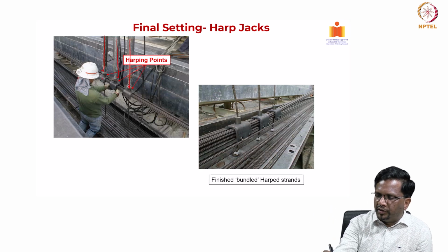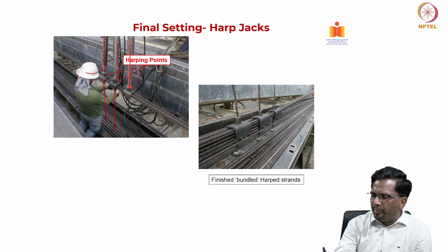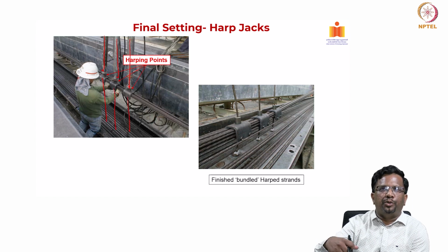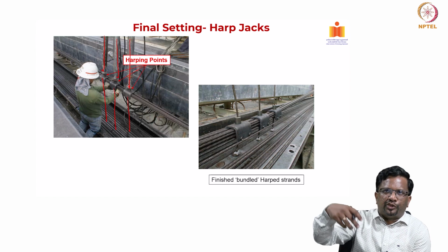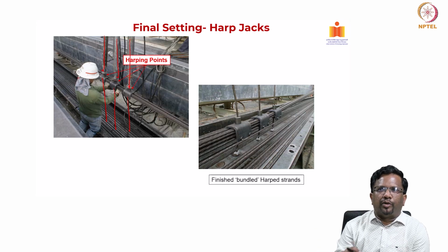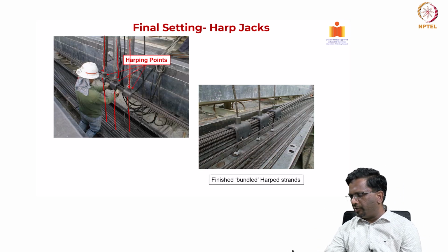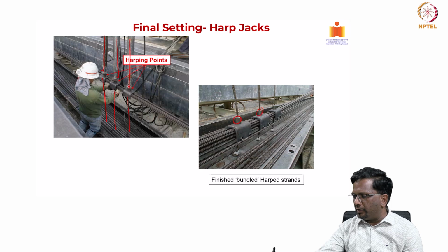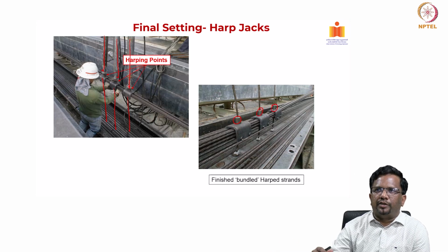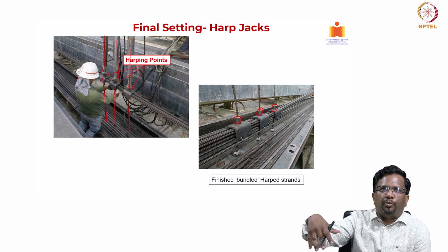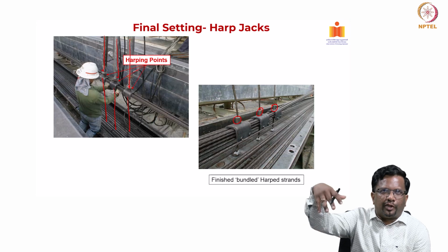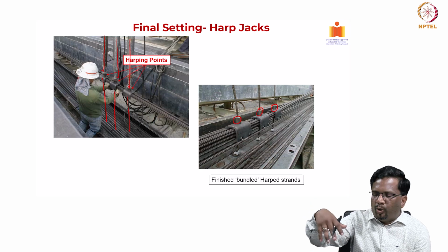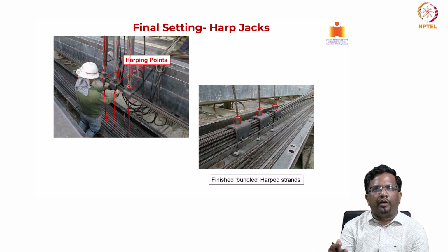For example, you see this is again a vertical cable that is helping you push this pre-tensioning cable to a particular eccentricity. Now you have an anchor here, right? So these anchorages are pushing it down. So I am actually applying a vertical pre-stress to the cable itself. Now how will this particular cable be anchored?